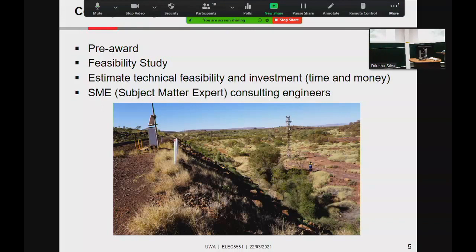None of the data radios were like for like replacement. So it wasn't something where you unplug and plug. We had to do the whole wiring, power system and everything. And then none of the major companies that we could find could guarantee a supply for the next 20 years. So it turns out we could find a good data radio, but we could be at the same stage in 10 years' time. So fiber means for good.